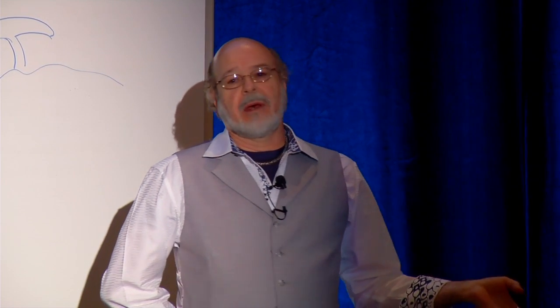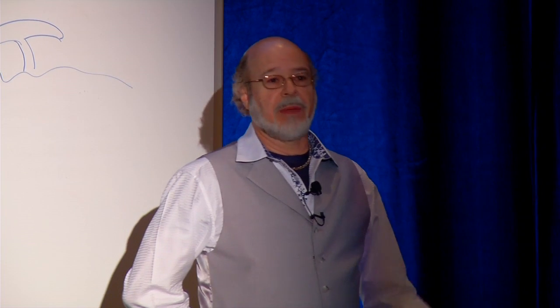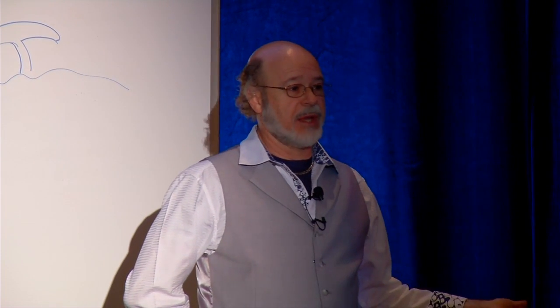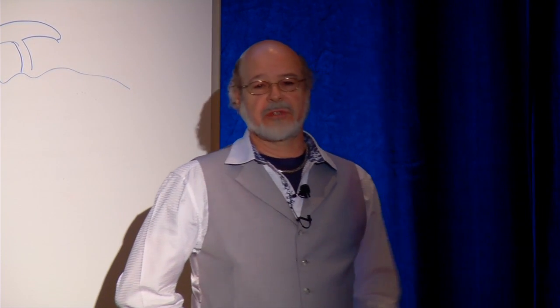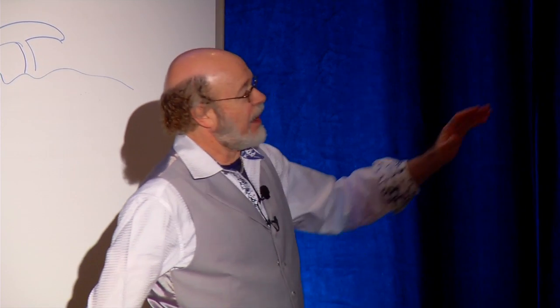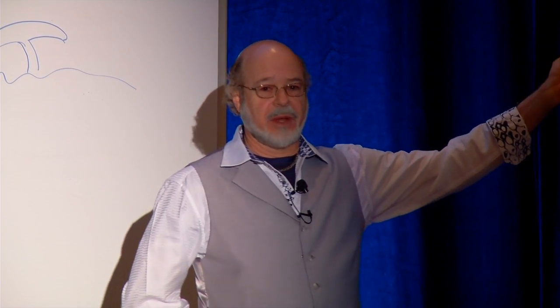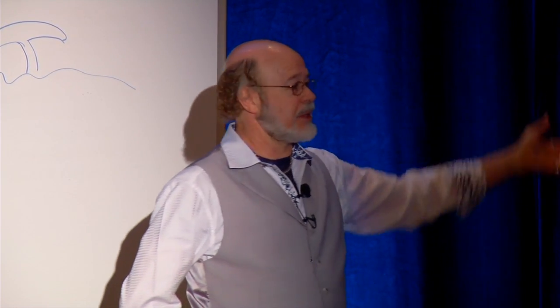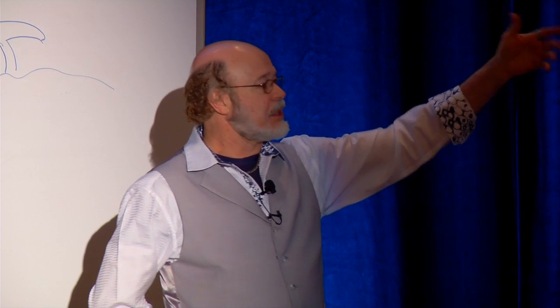I need to know that there are exterior doors on the project because, well, what we do is we close the header off so that when the door opens up and it fills up with water in the top channel and the door closes, it doesn't drench my customers and owners. So I want to know that, and I want to know, okay, yeah, I do have galvanizing because that's a default. But the project architect doesn't need to know these background things. He doesn't have to. He only needs to be able to tell me some very basic things here.